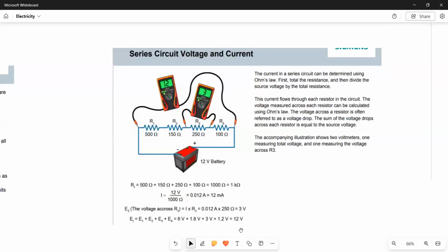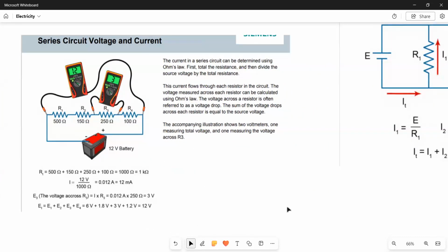So let's take a little example here. Here's a little circuit. What you're seeing there is what we call a multi-tester. They're all over now. I bought a very cheap one from the Chinese, and I've been using it every day. If you want to know the resistance across all these resistors, notice where the probes are placed. If you want to know the resistance of this one resistor, notice where you place the probes.